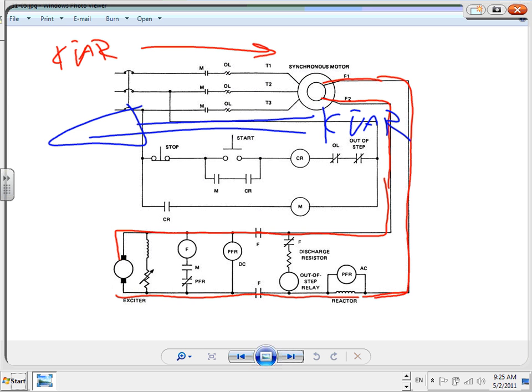Without getting into the control system, there's a control system that can adjust how much kVAR based on the horsepower and the excitation and so forth. As far as you guys are concerned, you're going to size these, and I'll show you how to size them in kVAR. I want this amount of kVAR, then there will be a chart that says this amount of kVAR is equivalent to a 50 horsepower synchronous motor. Bam, then I need a 50 horsepower synchronous motor. Most of what I've done is really capacitance, so you don't have to worry about the horsepower of the synchronous motor. Just a 50 kVAR capacitor, done deal. Any questions, guys, about this?